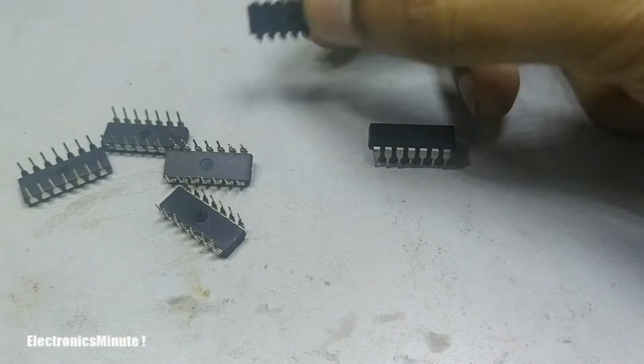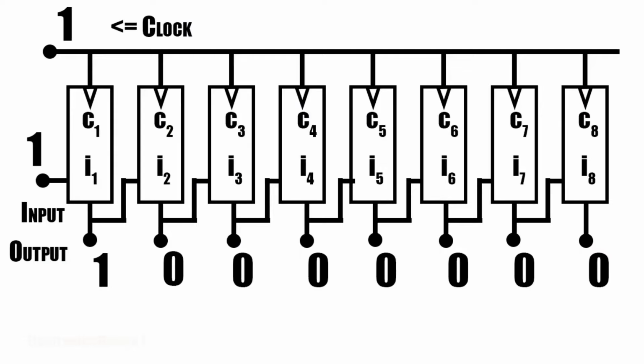A shift register makes an output of logic high or low, whatever input is available on the rising edge of the clock pulse, and latches it in the first output. In the next clock cycle, it shifts the data one bit to the higher order and then shifts again in the next clock pulse. While there are multiple clock pulses with valid data, like the byte map, on the clock and data pins of the shift register, the output pins will have the same byte after every 8 clock pulses.